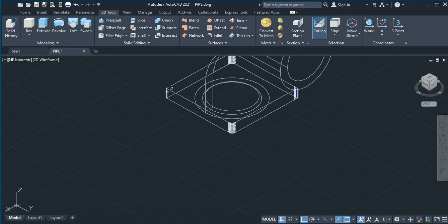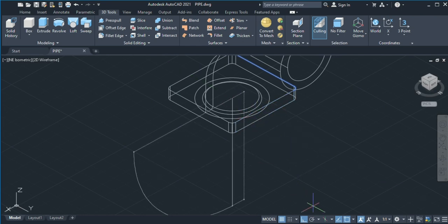You can go for the 3D tool, that will be chamfer. For this one I'm doing edges fillet. Edges fillet, we want to make the edges become smooth. For this one it is mentioned fillets of 20 radius. So edges fillet, type the radius 20 and then click the edges that you want to fillet.